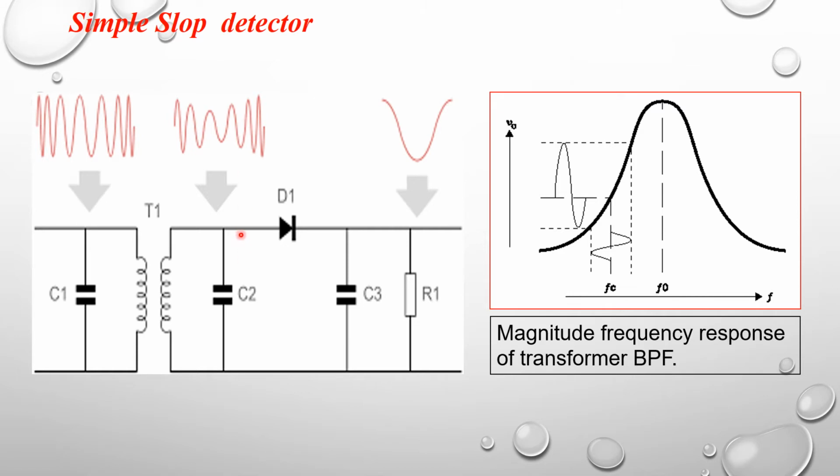Whenever the input is minimum frequency, we receive the minimum amplitude signal. The output of the tuning amplifier circuit is connected to the envelope detector. We know that the envelope detector consists of a diode, resistor and capacitor. Here the resistor and capacitor are connected in parallel, and it acts as a filter. The positive terminal is connected to the transformer, and the transformer terminal is positive, so the diode is in forward bias condition. So it conducts the positive value.